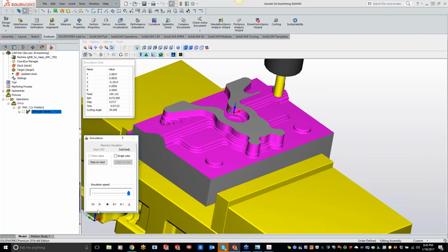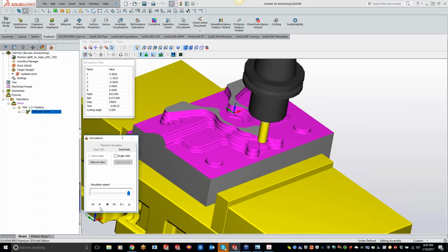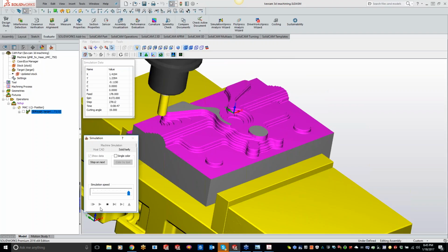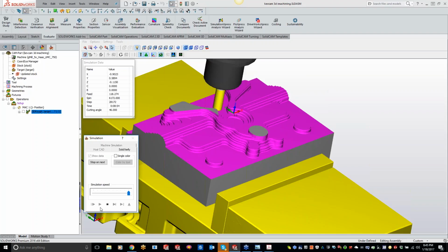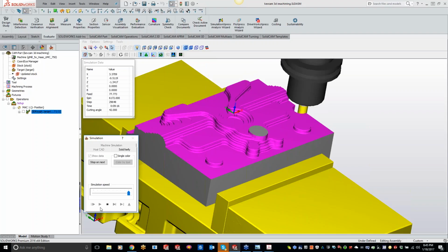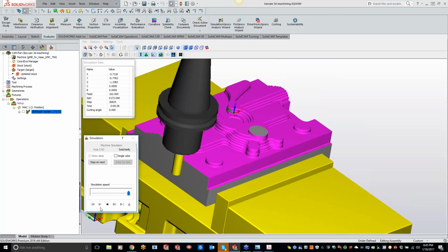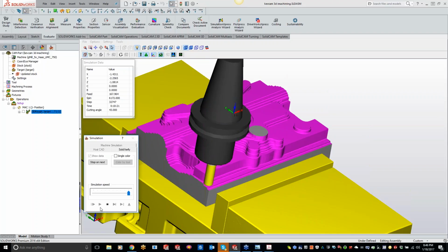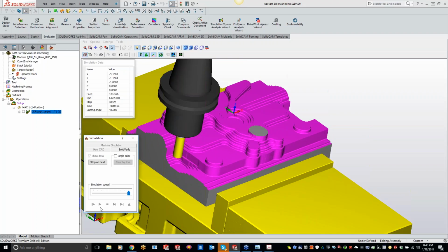What Brendan is saying is, iMachining adapts for thin wall features. As soon as it knows that it's getting into a thin wall, it actually changes the feed rate, and it's going to change the approach angle of that end mill, so we're not breaking through. And as you're breaking through a thin wall, you get that little piece that's going to curl around. A lot of times it's not going to break an end mill, but it's a good spot to chip out a tooth, or not get a nice finish, and that little tiny slug is going to wrap around into itself.